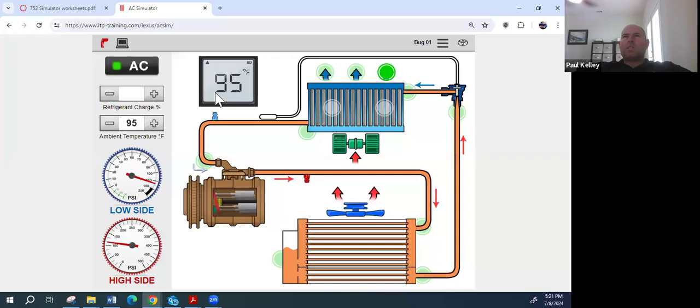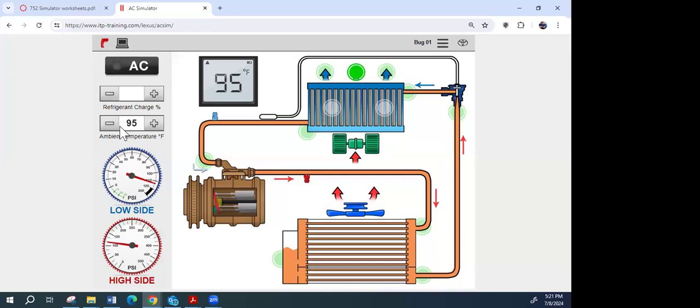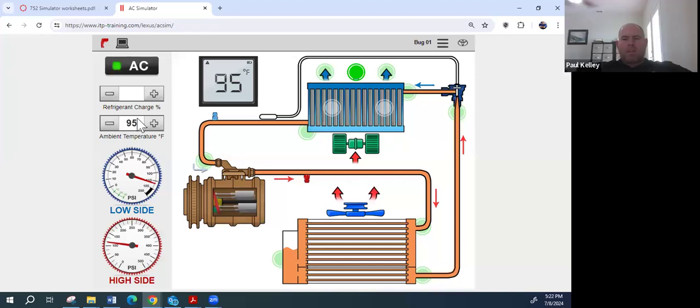And do you see what the temperature reads? When I picked up the thermometer, it showed me the temperature. I could put on multiple points. But if you look, the first thing we do is just measure the air coming out of the vents. What would we call this? Is it blowing warm, cool, hot, cold? Is there a better term we could use? What's the temperature outside? Do you remember? Ambient temperature. Yeah, I agree. It's blowing ambient.